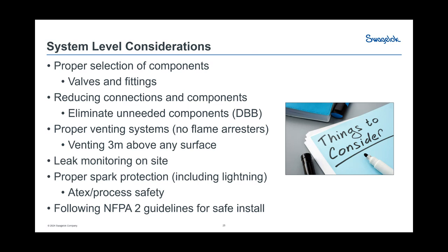People have also tried to do flanges all the way down to 1/2 inch, and the flange design is a huge surface area, relying on a gasket being compressed, relying on materials of that gasket not to permeate all the time. Not a great design for high pressure areas. Really, your best approach for fittings is tube fittings. Valves need to be careful with.